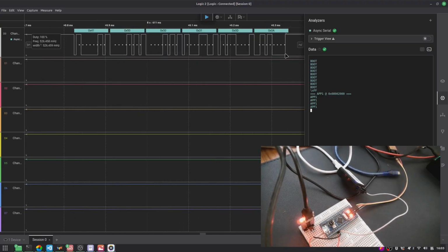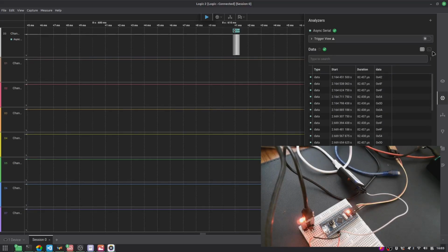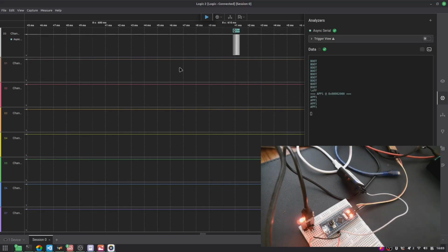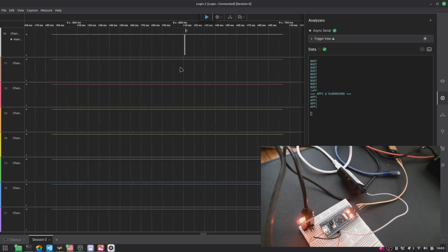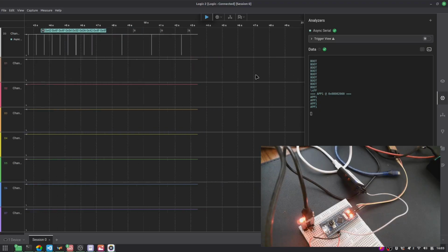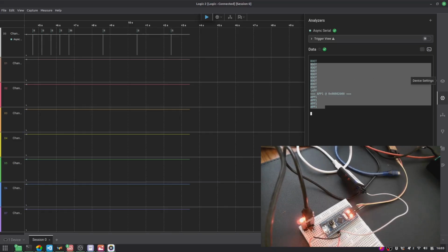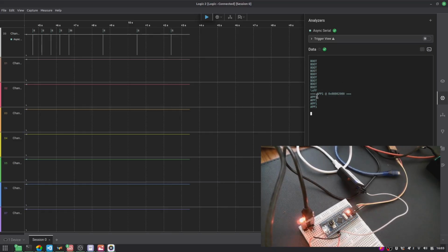So this is a sequence of bytes. I think this is a boot message, BOT. Similarly, we should also be able to see the chunks when the bootloader is sending bytes or the flash loading is happening and the bootloader is receiving bytes from the flash loading application or the Python script. If this font is small, I'll try to zoom in, but you can see that the boot message appears along with a jump to the application.